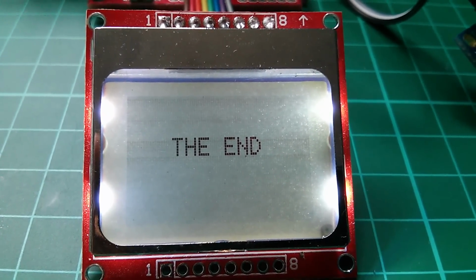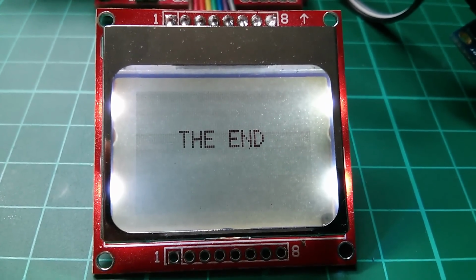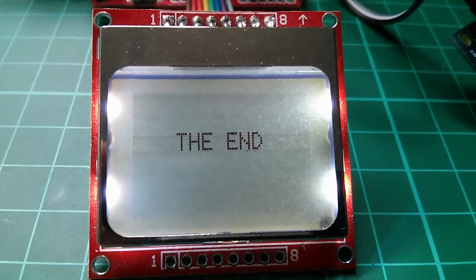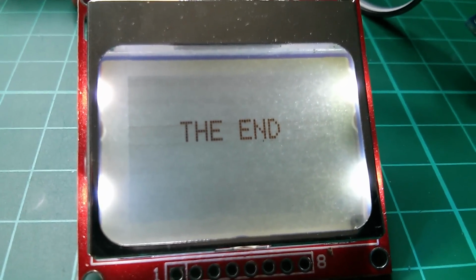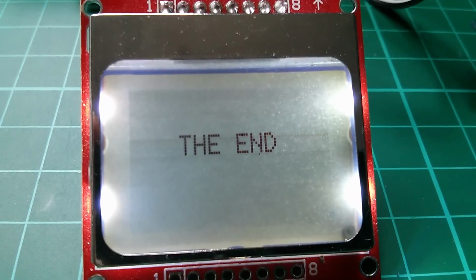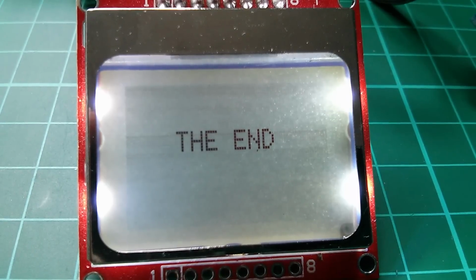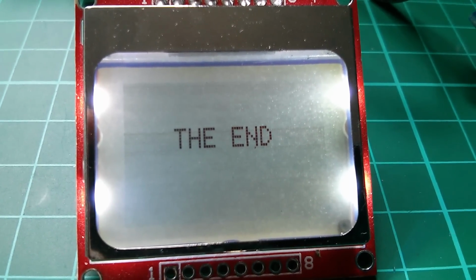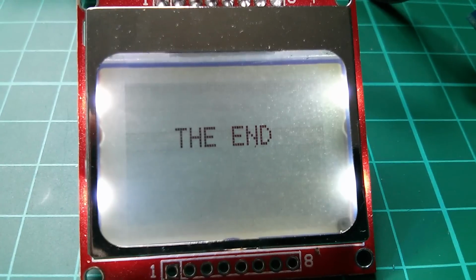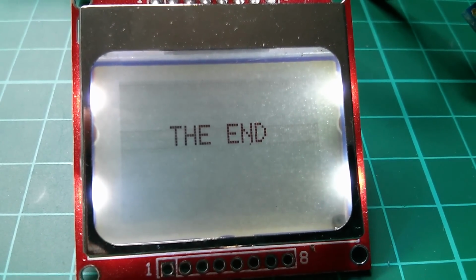Now in the first part of this tutorial, I was fairly adamant that these displays work perfectly well on 5 volts, and there's none of the vagueness that the seller of my original LCD was talking about, but I'm not so sure now because I'm getting little bits of swirl, just movement on the switched off pixels. It's about as good as I can get it, and that's why I've changed the bias setting rather than contrast, because I found it just gave me a better result. So it is possible that at the higher voltage these displays are just slightly more problematic, but if you fiddle with those values you can get a reasonably good result.